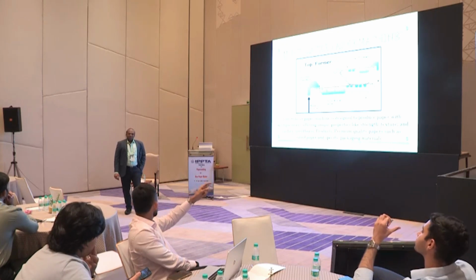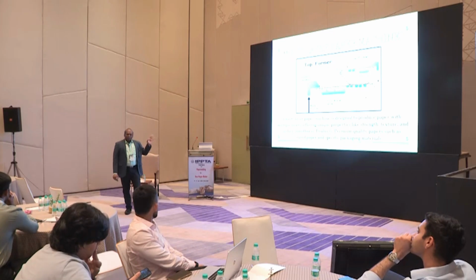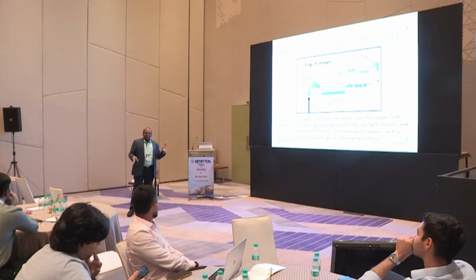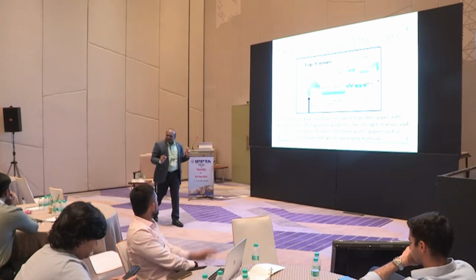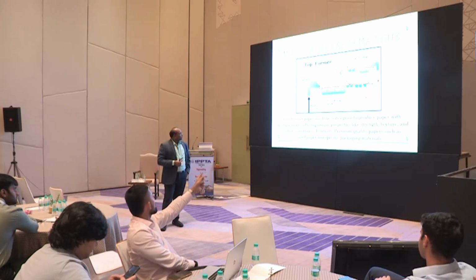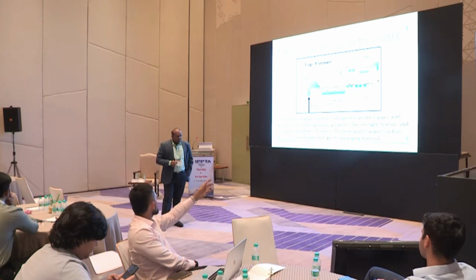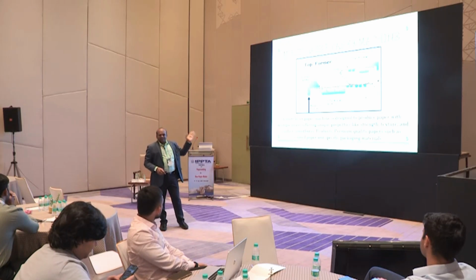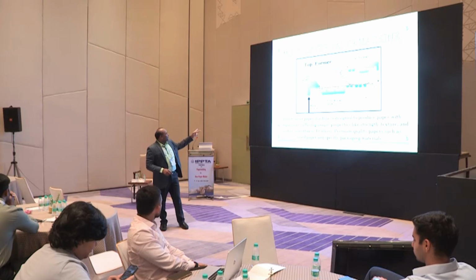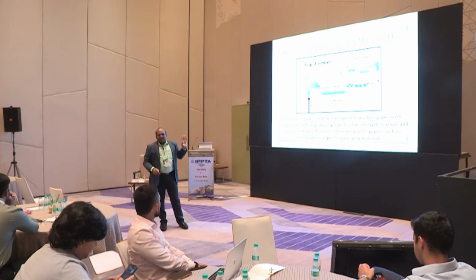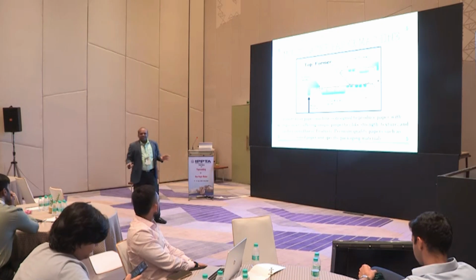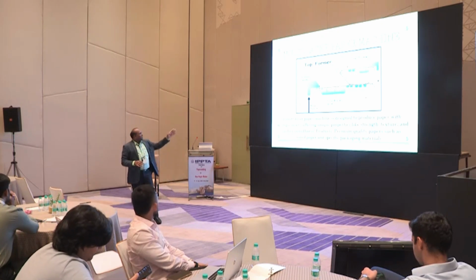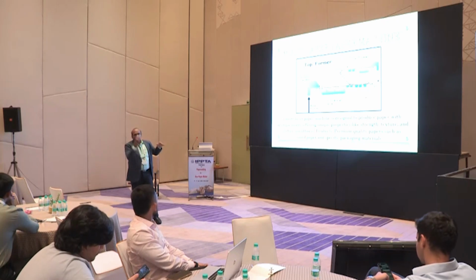No, actually it's a different concept. It is not the same. Maybe it is looking the same, but it's a different design. What you are asking, basically, is that your top former has a second head box also. Yes. But is it possible to have a top former without a second head box, right? Yes, that's an entirely different concept, a different design. For example, we can't operate this as a top wire former without that head box. What I am saying is, now two layers are not running, only one layer of paper I am taking, so that we can load it on the wire and remove the water. It is not possible.